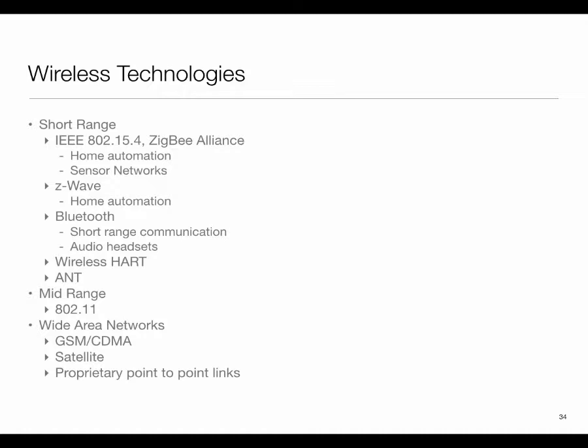So you'll find it in quite a few places. 802.11 sensors are there, but they basically go through this mode where they can act as an access point so that you can talk to them. And one very common practice I see nowadays is that during setup mode, they will act as an access point. You talk to them, you pass to them configuration information, and then they switch and hook up to the 802.11 network in your home. You go through this two-step phase to set things up, because otherwise you get this device and it doesn't know anything about your home network, it doesn't know how to connect to it.